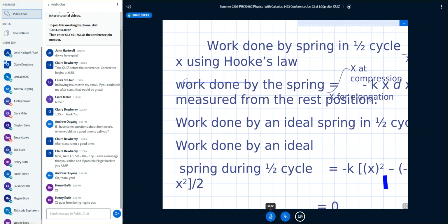In fact, they were talking about the integral here is exactly what determines, of course, the area under that curve. The kx squared really looks like a 1/2 of a base times a height type of calculation. That the graph represents oscillation of an ideal spring and no friction between the coils. I've sort of said that a few times because it's critical in these equations.